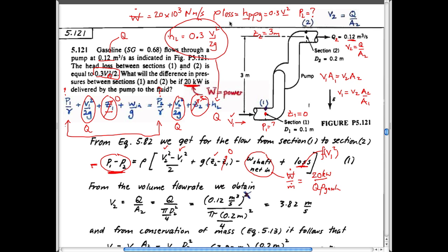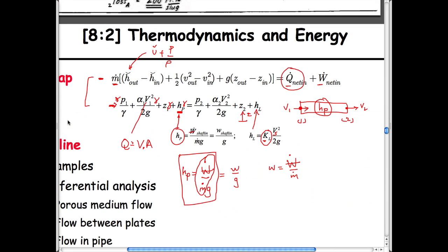I think it's good to use a set of equations. When I remember Bernoulli, I always remember it in this form, but you can always move between them. By far the more important equation for us to use is going to be the second one. We used this once for a quick enthalpy question, and we've used this many times. It's useful because it's written all in terms of lengths. This has to be a length, so if the numbers are huge, you've probably dropped a dimension somewhere or not done a conversion correctly.